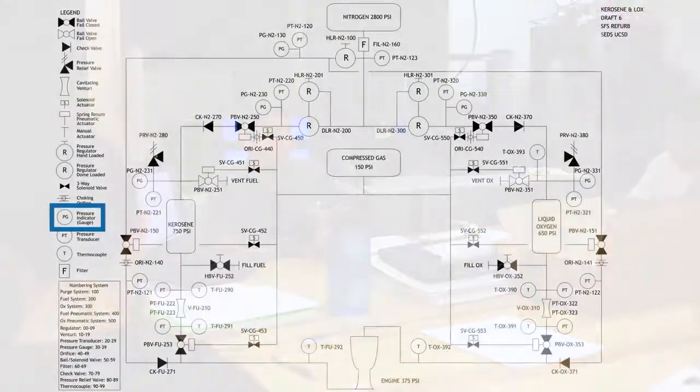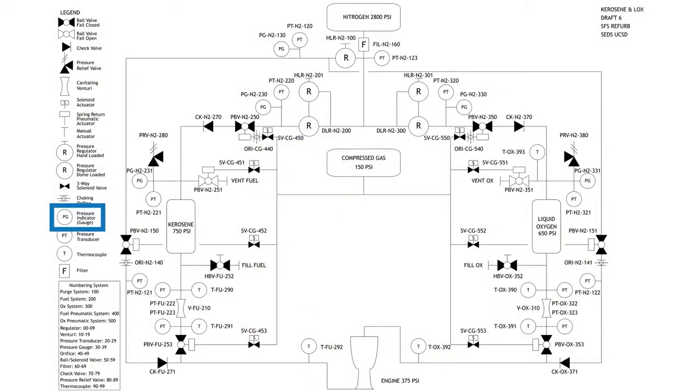Pressure gauges, you guys have seen them everywhere in your life. Basically, it's just a mechanical dial that moves based on what the pressure is reading. I'll talk more about the positioning of our gauges. A pressure transducer takes the pressure that you put up against that transducer and turns it into a Hertz signal, and then we can read that Hertz signal and transform it into a flow rate or a pressure. The pressure that we're going to be reading is going to be a static pressure. If you guys have taken fluids, you'll know the difference between dynamic and static pressure.